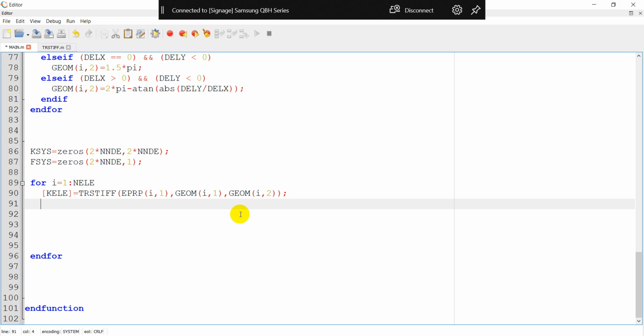You don't see the benefit so much in here because this is just a truss structure. The plug-in operations actually don't take you so much time. But if you imagine you go with some other kind of structural element like plate bending, you might end up with 12 by 12 degrees of freedom, a 12 by 12 matrix. 12 by 12 matrix, 144, right? You cannot write 144 lines of code in order to just take care of one element. It is not a good idea.